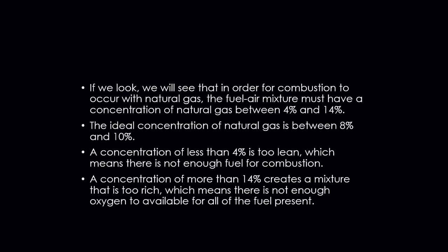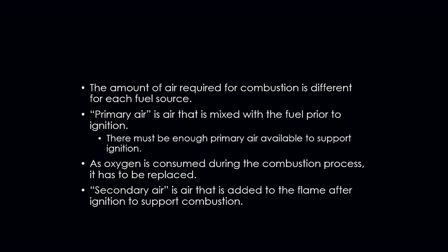A concentration of less than 4% means it's running too lean. We're not getting enough air to support combustion. And if that were to happen, we are not burning off all those carbon molecules that are in methane. So therefore, we will probably be sooting up and not achieving enough temperature to properly heat a space. A concentration of more than 14% creates a mixture that is too rich, which means there is not enough oxygen available for all of the fuel to be present.